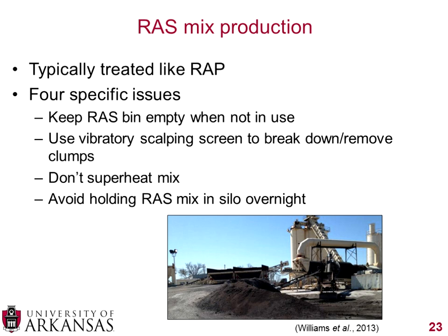There's a lot of asphalt cement in there, 20% plus, so superheating it can cause severe problems with your final product. And then they also don't recommend you hold the RAS mix in a silo overnight. I'm sure there's a lot of not good things that could happen. It could stiffen up in the silo. It could become hard to work in the field, hard to compact, so you want to avoid doing that.